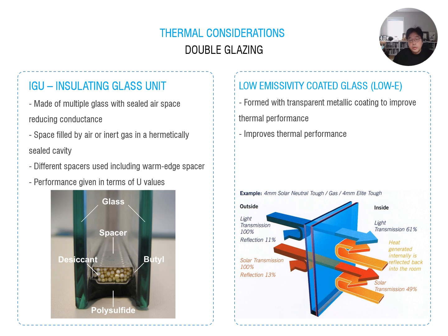So when you consider a double glazing or triple glazing system, we have to consider two techniques, which are insulated glazing, IGU, yes, IGU, and low emissivity coated glass, which is low E, we'll talk about it. IGU is the most common type in double glazing or triple glazing systems, and it is double or triple glass window panels separated by a gas filled or vacuum filled space to reduce heat transfer.